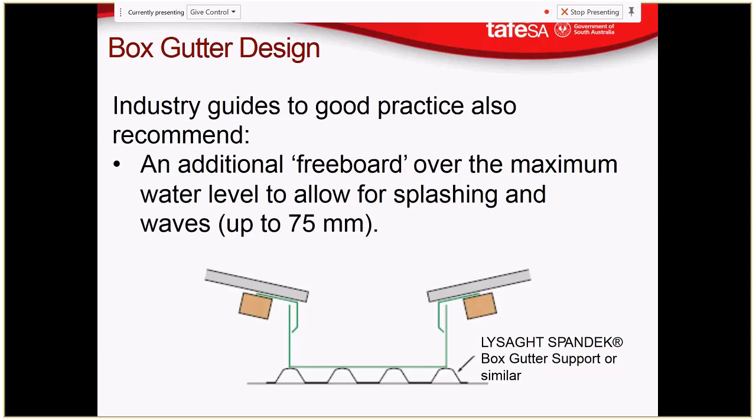These are just industry guides to good practice. What I'm saying in regards to box gutters is, where you've got plenty of clearance and depth and the ability to have a good slope on a box gutter, do it. Use it all. It's much better to way over design a box gutter than to under design it or take it right to the end.